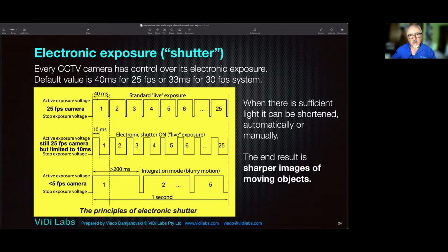This is one of the major stumbling blocks why with CCTV cameras that produce live streaming you can't see in low light as much as with a static or fixed camera. With your photographic camera, you can take very nice pictures in almost total darkness by letting the exposure be maybe 1 minute or 30 minutes if you want. But for us, in order to produce 25 frames per second, we are limited to 40 milliseconds as the longest exposure we can have.